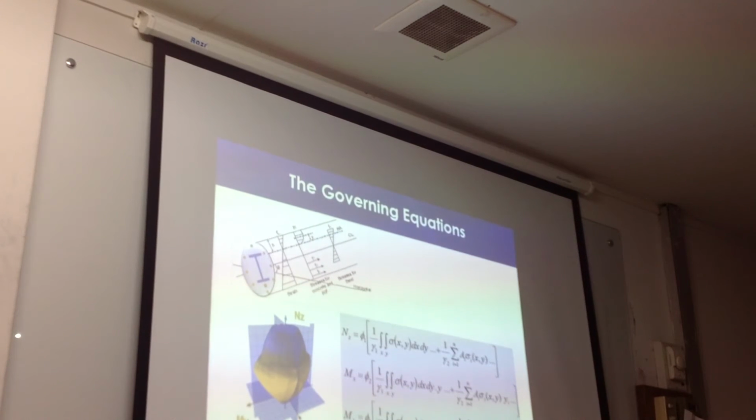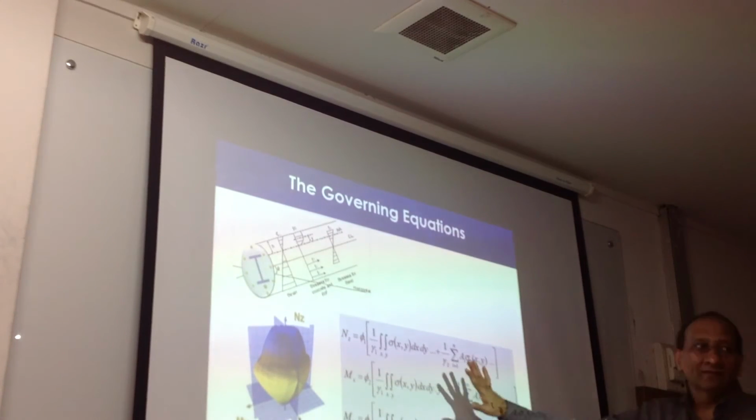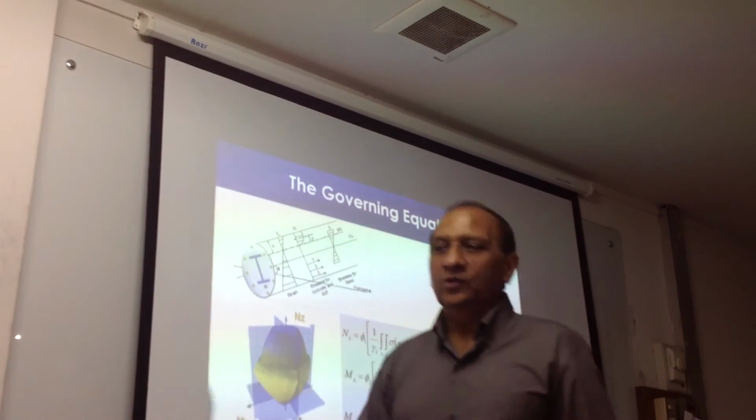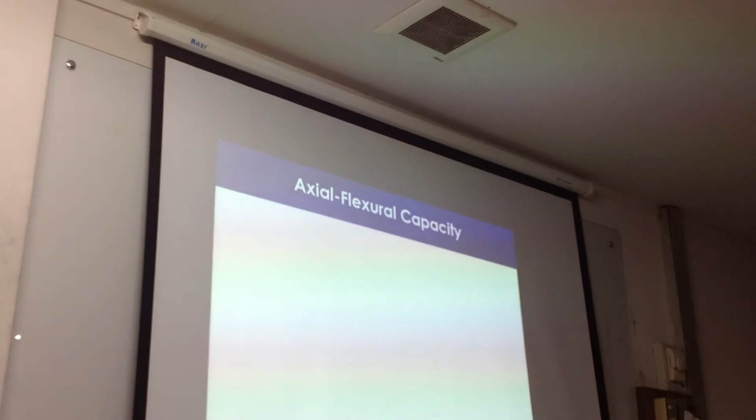But still it doesn't help me, because the reinforcement must be known before the surface can be generated. Right? So the next step is, we generate many surfaces for different reinforcement ratios and then quickly find which one we need. So it's a computational problem, but ultimately we use this equation for design. I will come back to this in more detail. Right now, just continue and give you the overall picture.